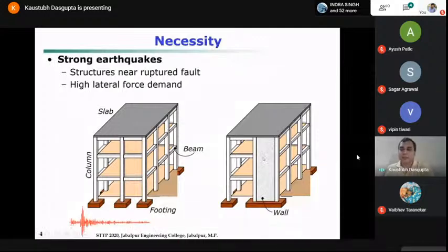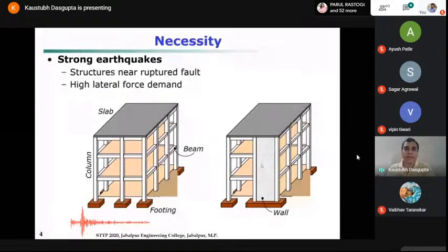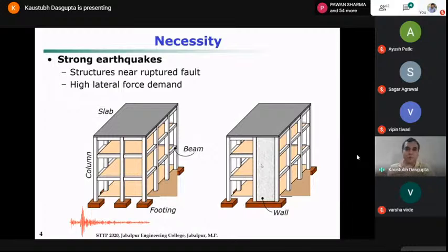So these have large lateral stiffness because when you consider the in-plane direction, in the plane of that wall, your effective dimension is the length and the width is the thickness. When we look at the stiffness contribution of any member, we look at basically the second moment of area, I. For a rectangular section, we know that it is proportional to the width and proportional to the cube of the depth, BD cube by 12.